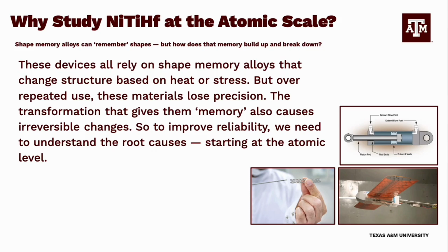Why study NiTiHf at the atomic scale? NiTiHf alloys are considered high-performance shape memory materials due to their high transformation temperatures and recoverable strains. They are used in jet engine components, deployable space structures, and minimally invasive surgical devices. However, these systems degrade over time. Performance losses like increased hysteresis, reduced transformation strain, and functional fatigue are common, and they all stem from what's happening